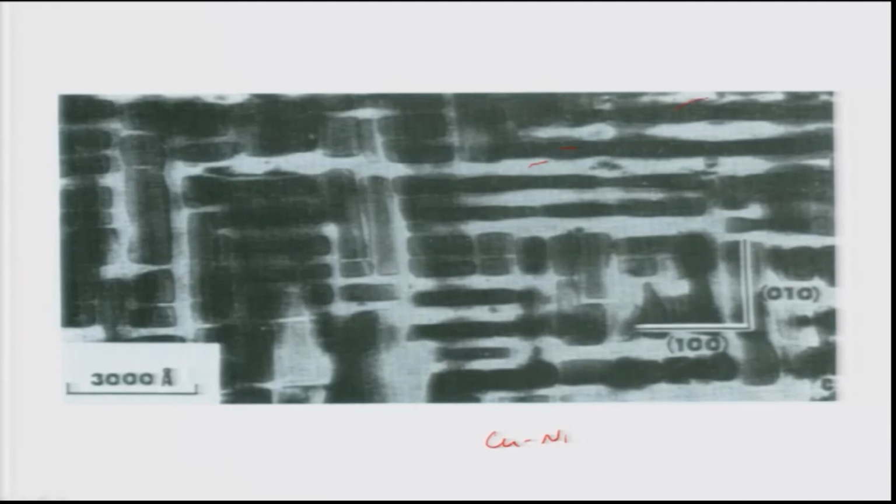This is like this, you can draw that, increase here in the middle, decrease here in the middle, okay. But that means if you draw for white phase, this will be opposite for the black phase which I have drawn. So in both directions it exists. In many of the alloys, this is iron silicon, it shows a very fine scale spinodal decomposition structure. Okay, so this is how the microstructure looks like.